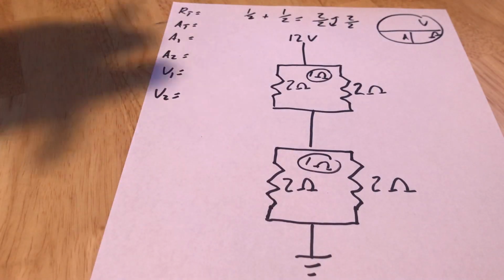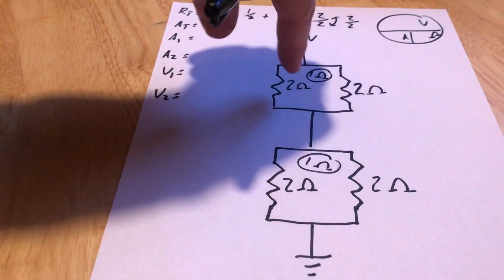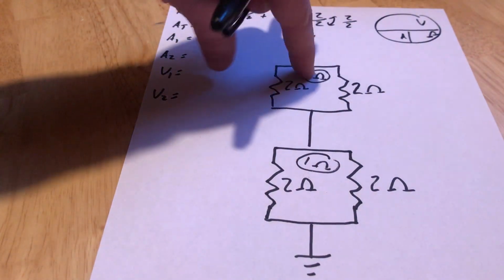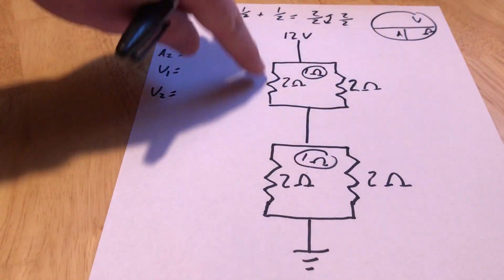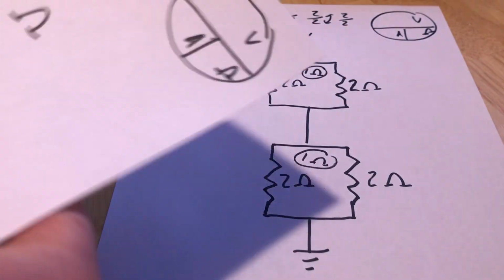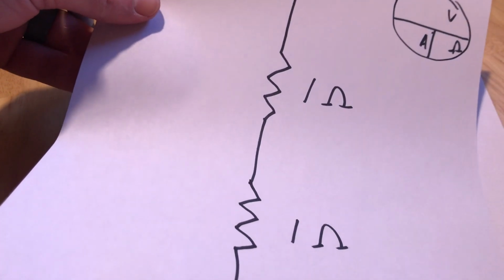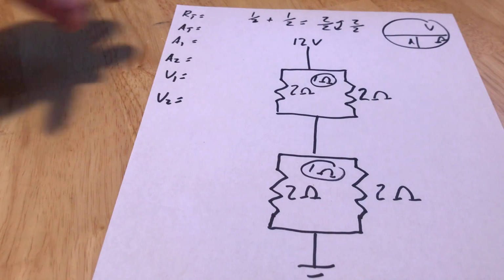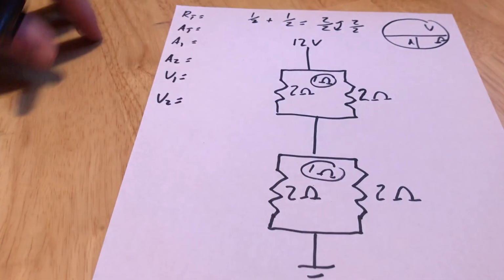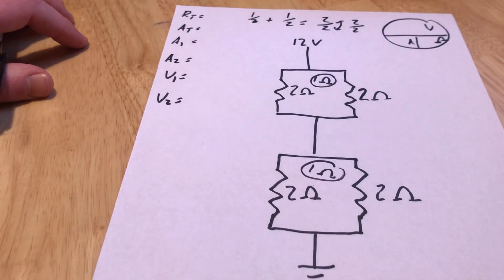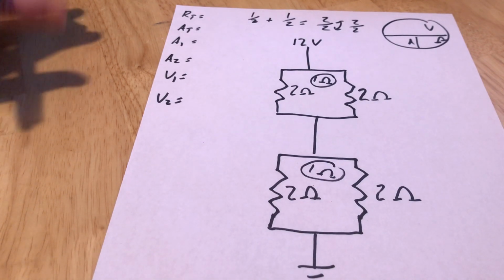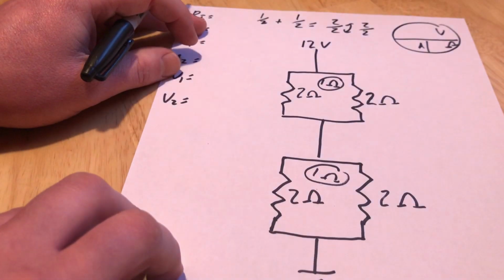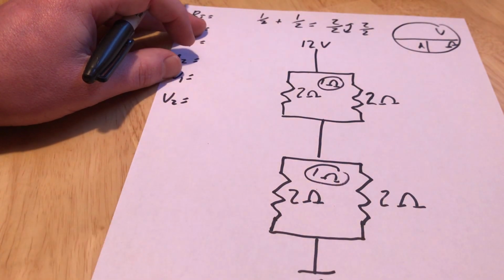And it wouldn't even matter if these 2 resistance values were different. If I had 2 different resistors, I did the math, it added up to 1 ohm. Each one of these legs is going to act like just a single 1 ohm resistance. The amount of current flow that goes through them will be a little bit different, but it will add up to be the same as just if there was a 1 ohm resistor in there. I know, I'm blowing some minds here. It's outrageous. Alright, so let's do some math, because who doesn't like math?